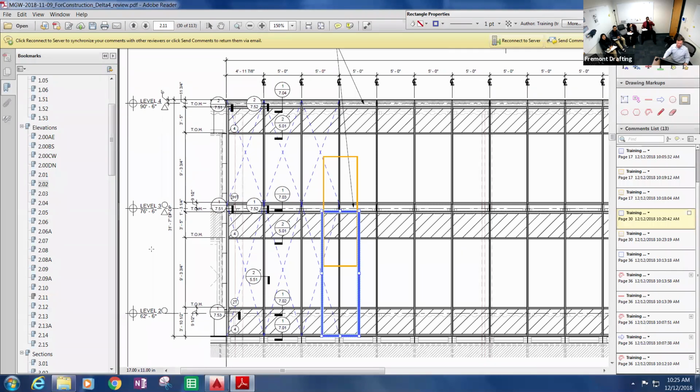And so then you'd have something similar, of course, at jambs. At a jamb, my wind load on that anchor is again back to quarters of units as far as the wind load. So that's picking up a quarter of the wind load there and a quarter there, and applying it here. And then as far as dead load, it's half of the unit below.